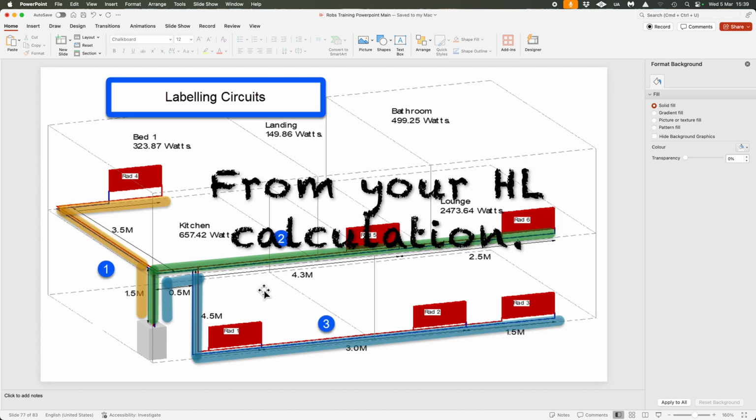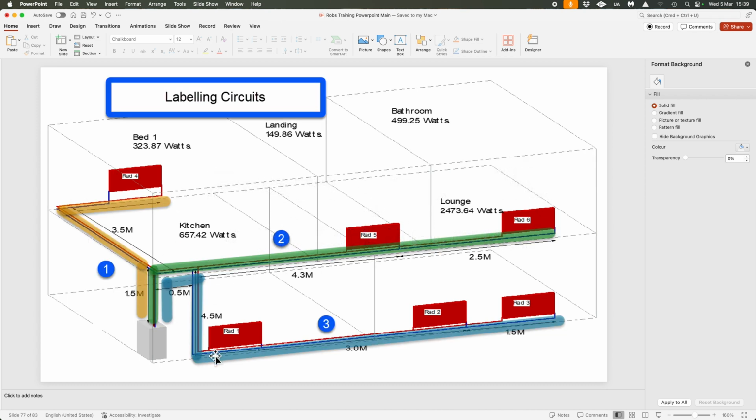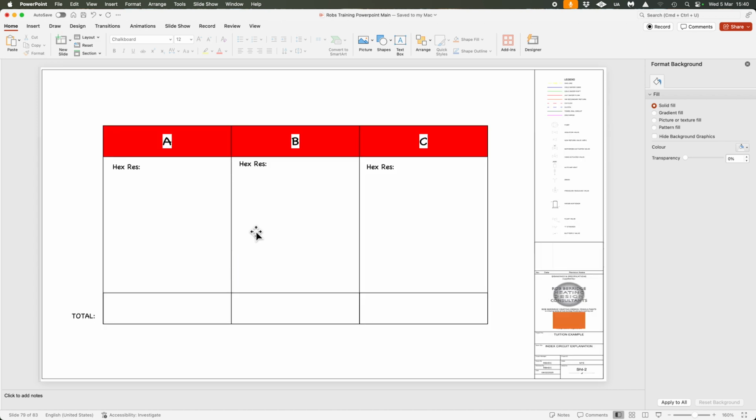So we know now, going back to this previous page, that we've got 3 circuits. So what I suggest people do is you draw out just a little chart like this of your circuits, so A, B and C, or circuits 1, 2 and 3, whatever it is that you want to do. And then we have a few things in here where we add them up as we go along, and then we put the totals in the bottom, and whichever one's the highest is going to be your index circuit, and that's how you would size your pump to that total pressure loss, or resistance to flow, across that one circuit. Let's just say it's B for argument's sake. If that was the highest circuit, you know if you can get over the pressure loss of that, it will get over the pressure loss of those, as we described in our previous triangle type chart, because this has got a higher pressure loss. So as long as it gets over the high pressure loss, it will get over these other two. So that is your index circuit.